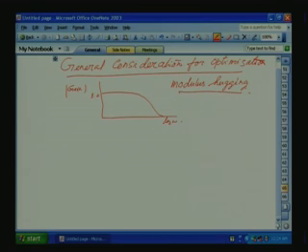Without pole zero cancellation, let us write down the transfer function. So now, without pole zero cancellation, omega feedback divided by omega reference is equal to Kn Ri by K2 Km into 1 plus Tn s because of our PI controller, and again because of our feedback time constant because of the filter.